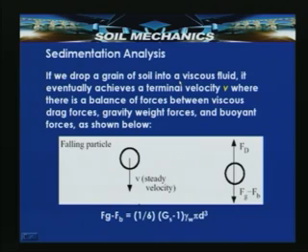Once we get the drag force on the soil particle, let us see what happens if you drop a grain of soil into a viscous fluid. It eventually achieves a terminal velocity V, where there is a balance of forces between the viscous drag force and the gravity weight force.